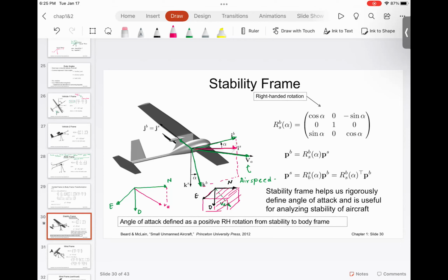Aircraft will not fly. Okay, so coming back to our discussion, that airspeed vector is at a diagonal. If you think about it, it is at a cross diagonal. If you look at the projection of that air velocity, VA, onto the north and downstream, what you get is an angle that is called the angle of attack. Shouldn't the VA be in negative kx? Yeah, I'll explain that to you in just a second.